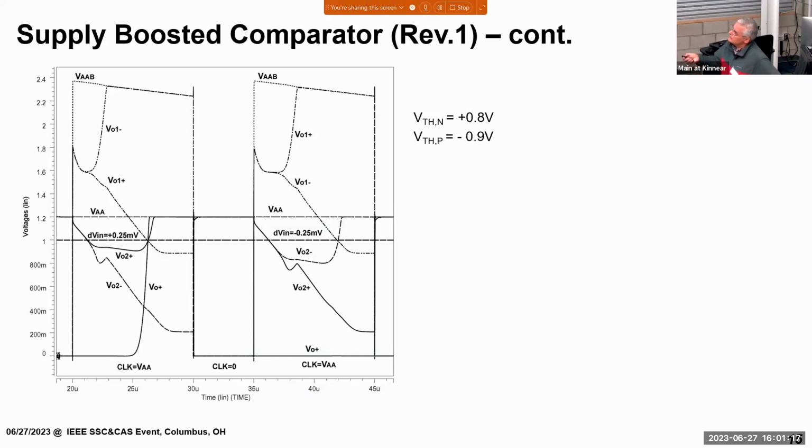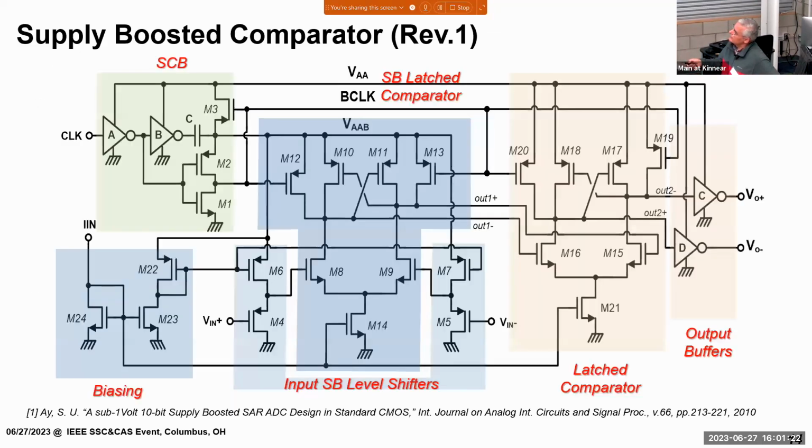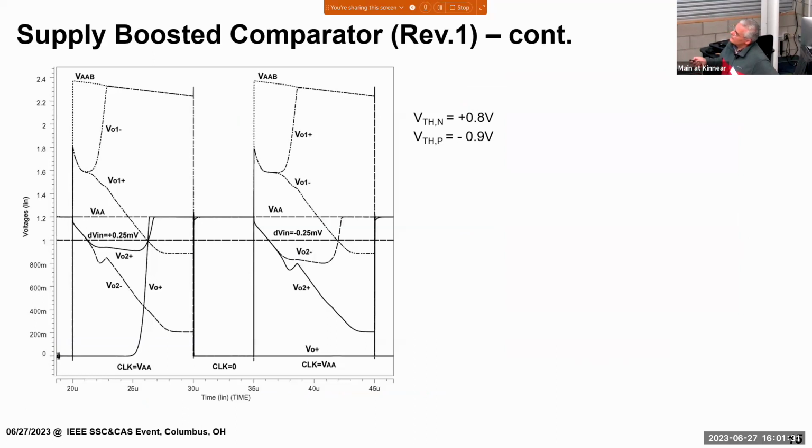And since the supply voltage is 2.4, and you are level shifting the signals up with ultra low power consumption there, that causes this voltage to drop, and everything is going to drop with it too. But since you are getting things done in maybe 6 microseconds or so, the second stage output is going to be able to make a decision with the difference that you have at that point. And from this point on, you don't really care.